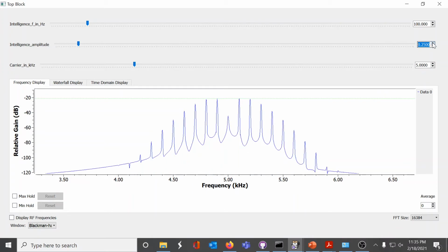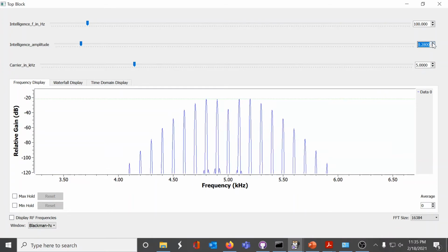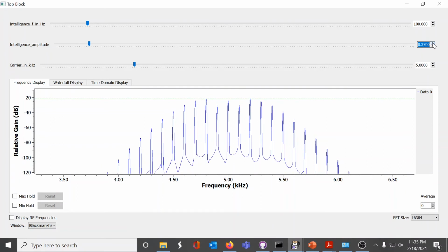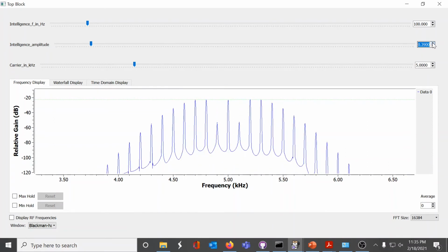Continuing on, there are a few other interesting points. So the carrier comes back up, and now you see the first sideband pair. The first sideband pair is going to 0. And we could continue on with that, ever increasing the bandwidth and watching these individual sideband pairs increasing and then decreasing in amplitude.